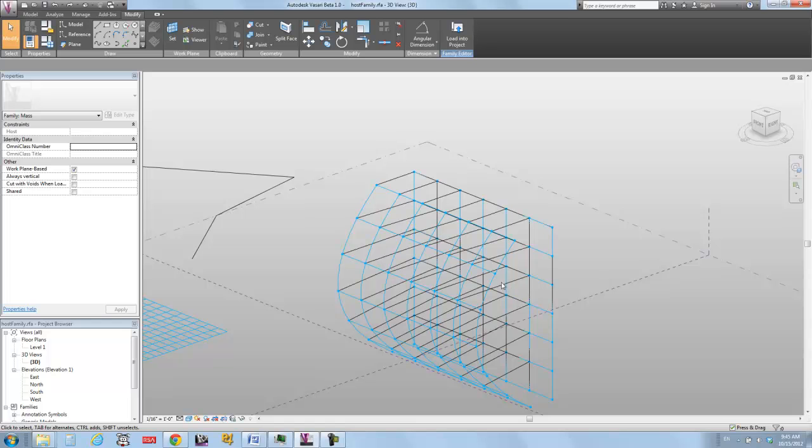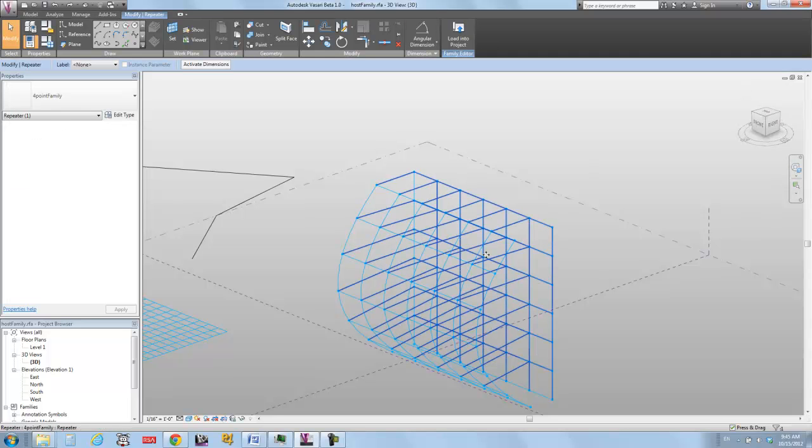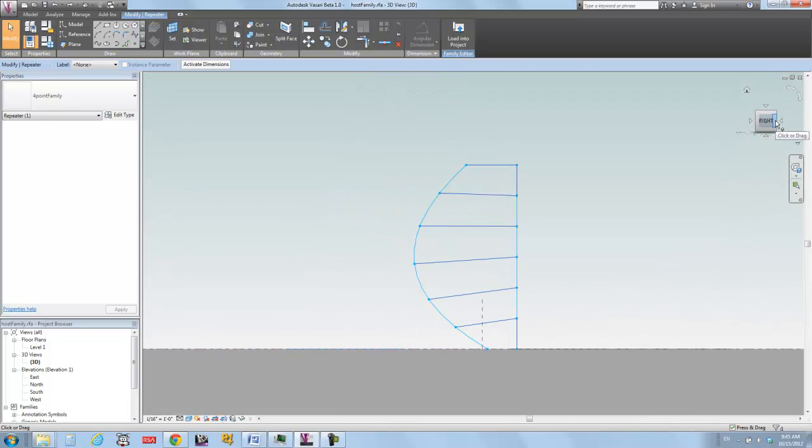One feature of this, as I'm selecting my repeater and hitting the right side of the view cube, is that you've got a divided surface out here on the curvy-wurvy part and on the straight part, and while they are both dividing by 6, they are not dividing in such a way that they actually line up, right? This is dividing into 6, but it's a longer surface because it's a curve, and it's just connecting the dots, right? So in most real-world applications, you want something that has some relationship to gravity and horizontality.